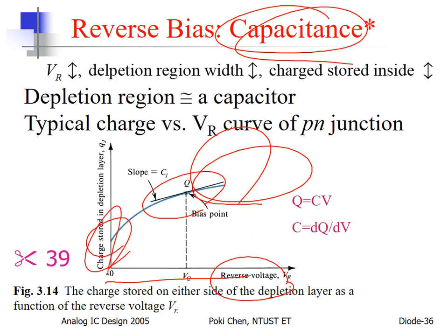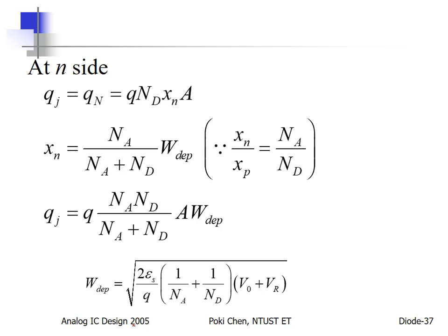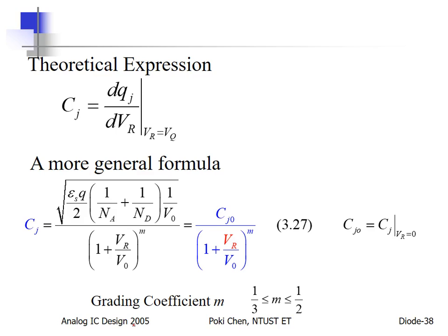If you would like to get very high frequency operation, please don't focus here. Around 0, that is the dangerous region for you, because it gets the most parasitic capacitance. It will slow down your operation.